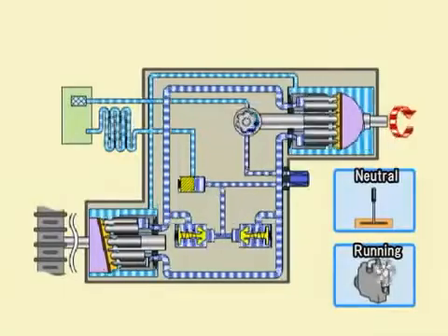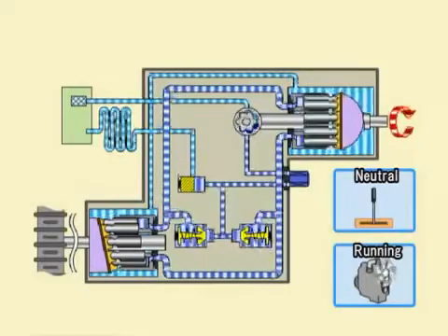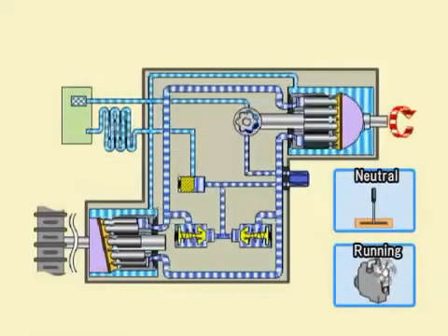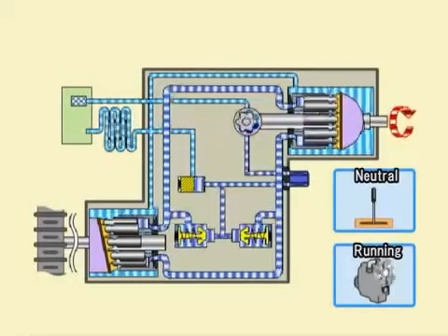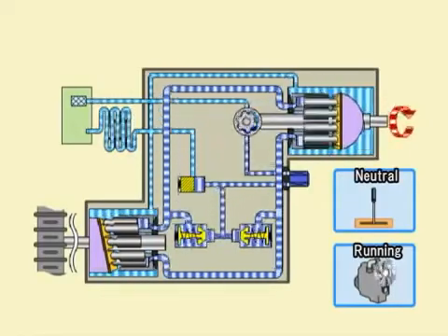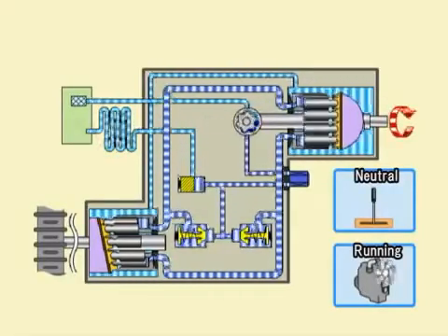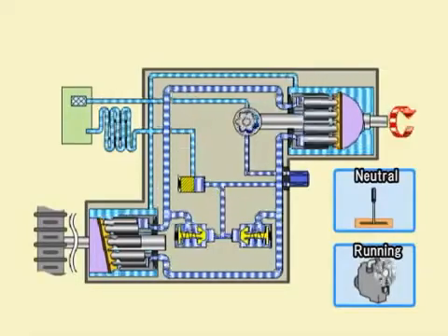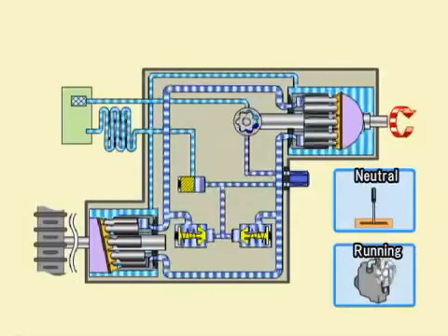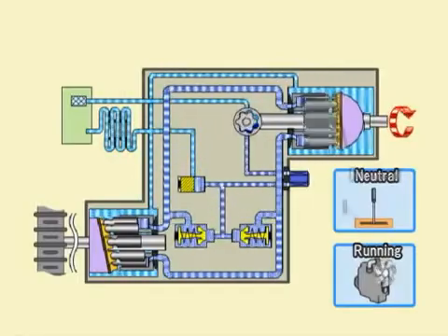Surplus oil from the charge pump depresses the charge relief valve, so it is always slightly open while the engine is running, and is also returned to the hydraulic oil tank. The HST is always operated with the oil at a high pressure, so the oil tends to heat up. This means it is necessary to cool the oil to maintain its lubricating properties and the oil film effect. The oil cooler is normally located beside the engine's radiator, so it is simultaneously cooled by the engine's cooling fan.